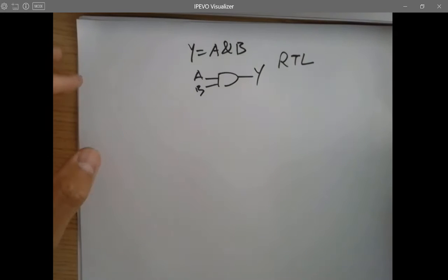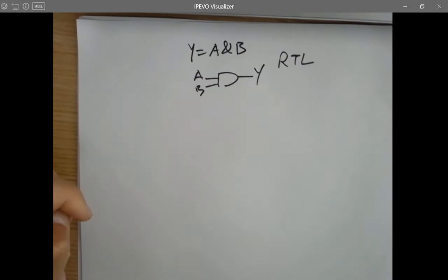There is a very specific acid you can use to etch every single layer, and then you can look at the second layer and duplicate it, and then the third layer, until the very bottom layer. So you can reverse engineer everything, right? Sometimes they try to protect their IP or their layout design. They will put some dummy circuits in there, trying to confuse people. It's not useful at all for the circuit, but it's just trying to confuse people who are trying to reverse engineer the circuit. It happens a lot.